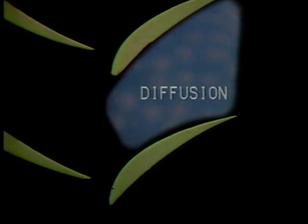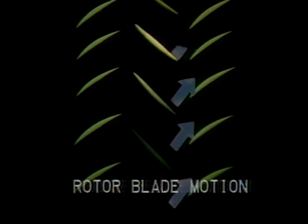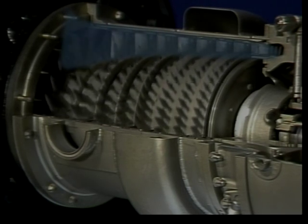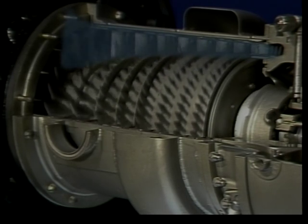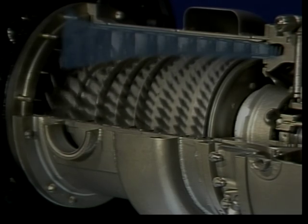Won't the air eventually stop if we keep slowing it down? No, it won't stop because two things are occurring which maintain air velocity. First, the moving compressor rotor blades add energy to the air and force it along to the adjacent stators. You remember that the air path along the compressor's length is decreasing in volume. Let's look very closely at the space between one set of rotors and stators.